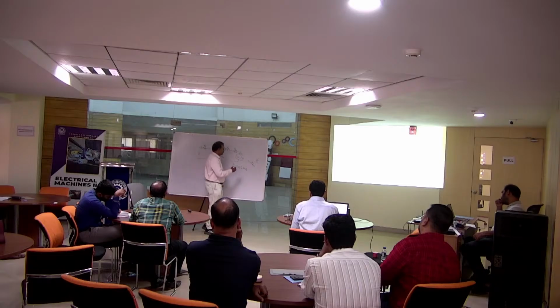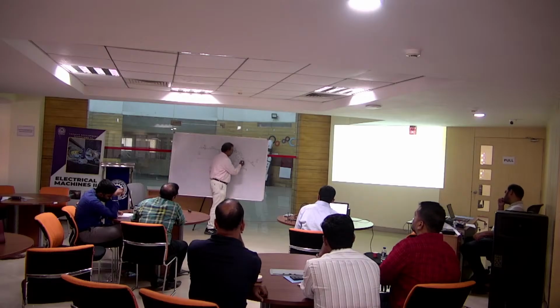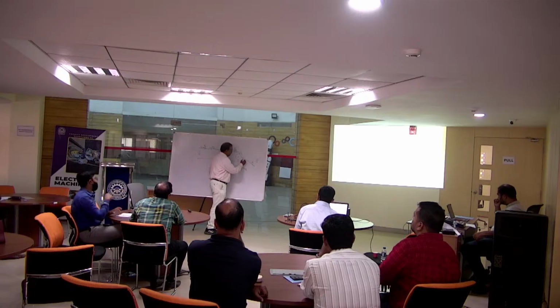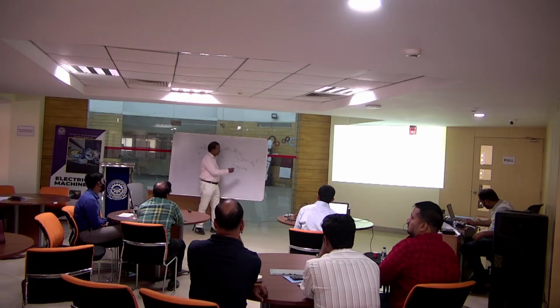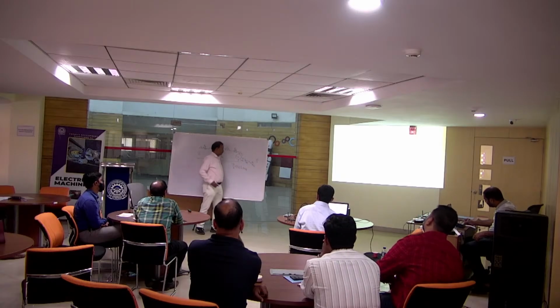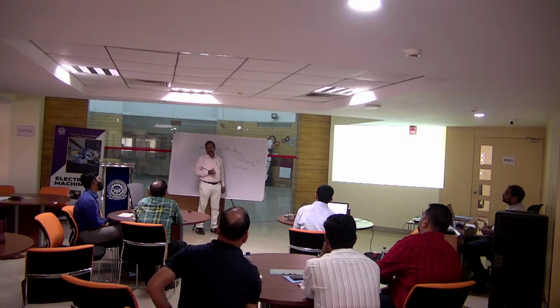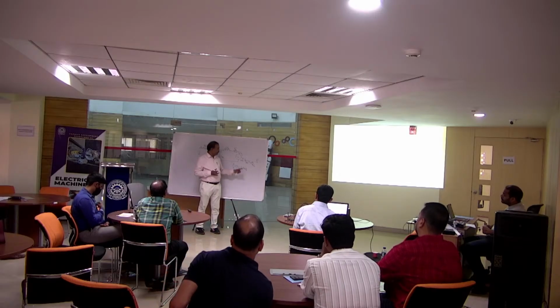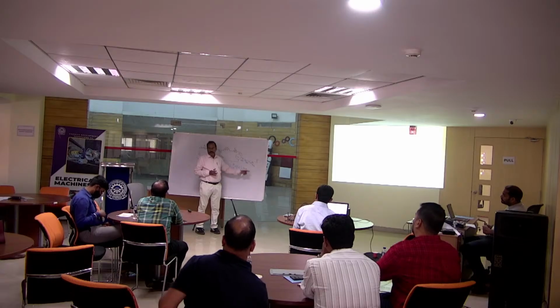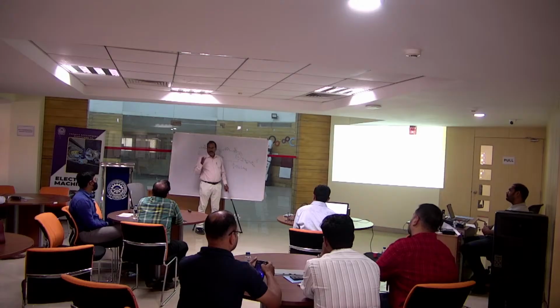Now the same thing, another instance. We make it like this. Let us say I am giving it like this, 180 degrees. This is IR. The angle between VR and IR is, I am saying, 180 degrees; it can be less also. So voltage and current are in opposite directions. So it is giving power. It is acting as another alternator. It is supplying power. Power is negative in this case. In the earlier case, power was positive. In this case, power is negative. So it is giving power.